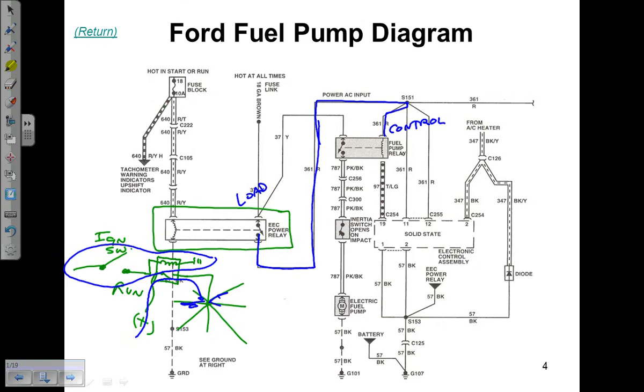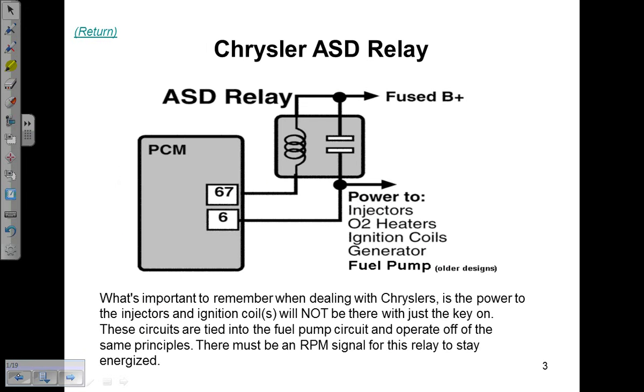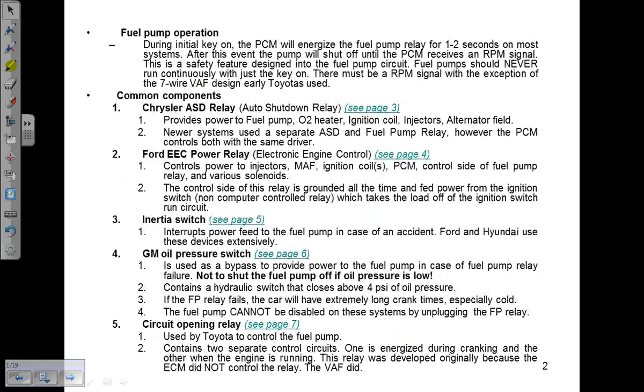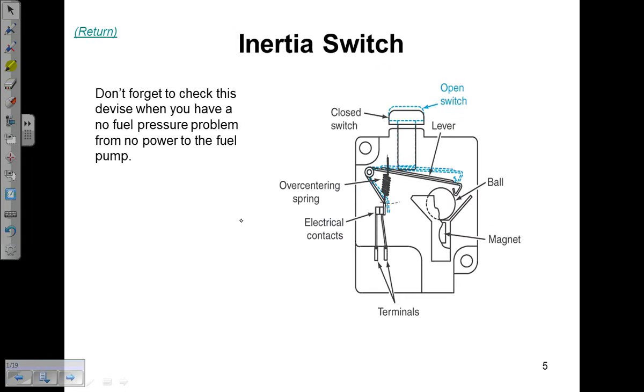So it's kind of weird. Load side of one relay controlling the control side of another relay. That's Ford. Something else in this picture we can talk about while we're here would be the inertia switch. An inertia switch on Fords. Two manufacturers I've seen inertia switches on, that's page 5, would be Ford and Hyundai.